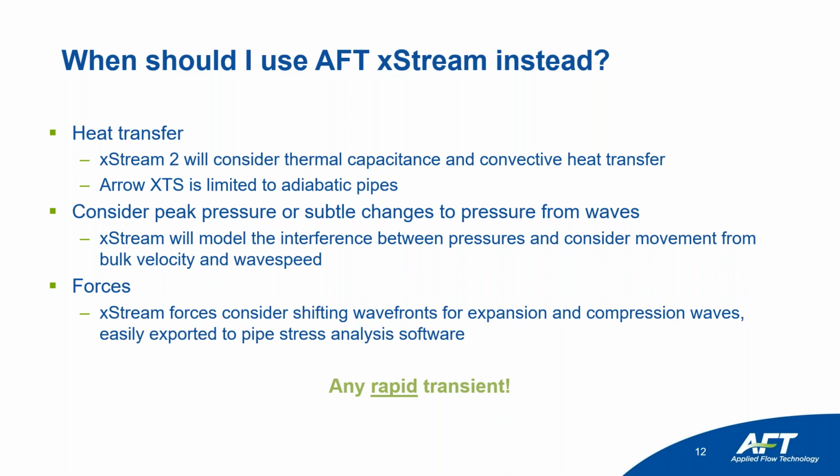So any rapid transient, and hopefully we've reiterated enough times the distinction between what we would call a slow transient, where it's okay to go immediately steady state to steady state, versus a rapid transient where things can change throughout the pipe itself.